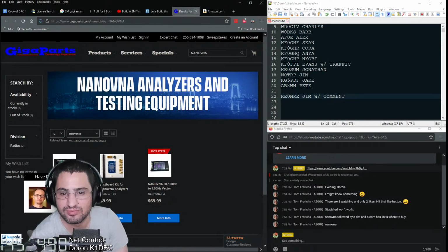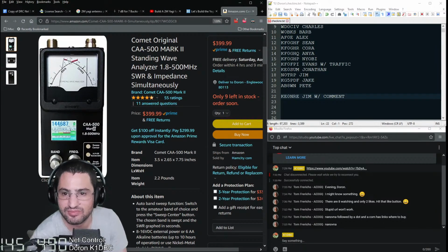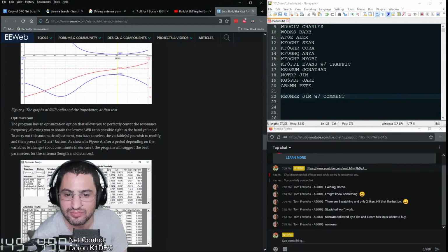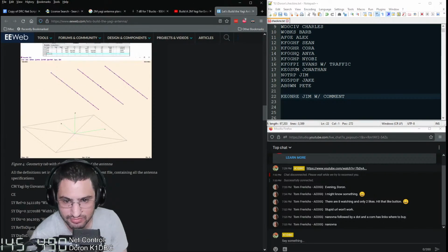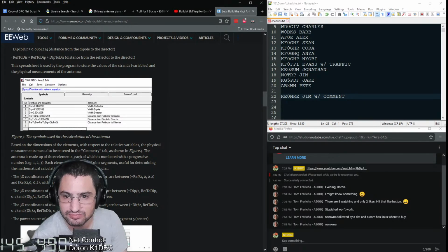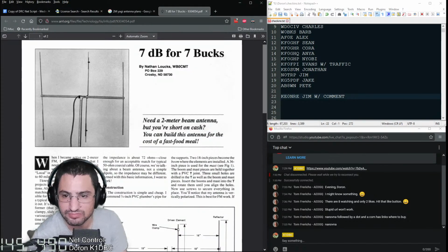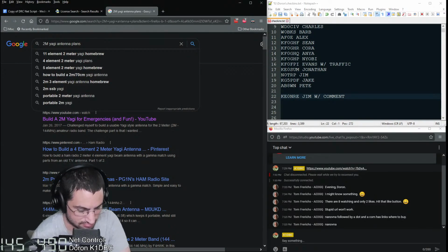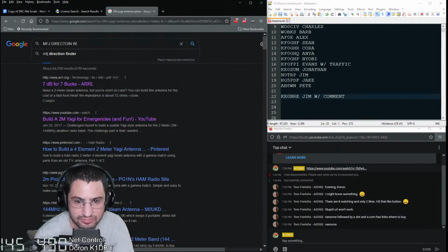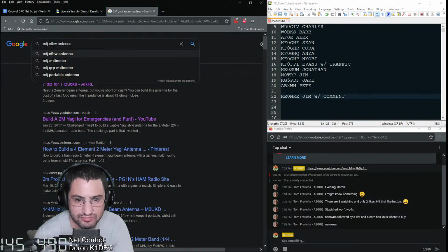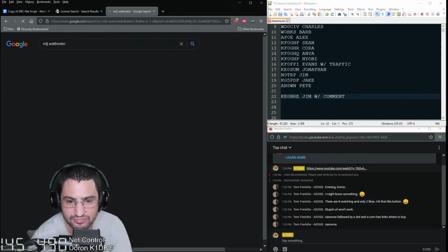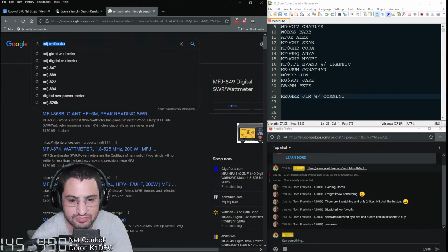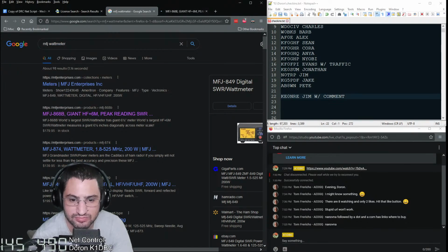Thanks, Daron. I've been listening to this very interesting discussion about antenna analyzers and the NanoVNA, and I thought about another alternative that could be helpful for tuning VHF and UHF antennas for those people who are building them, and that is a directional watt meter. I think MFJ has their 849, which will read not only HF but VHF and UHF power, and it'll also compute the SWR from the forward and reflected powers that it measures.